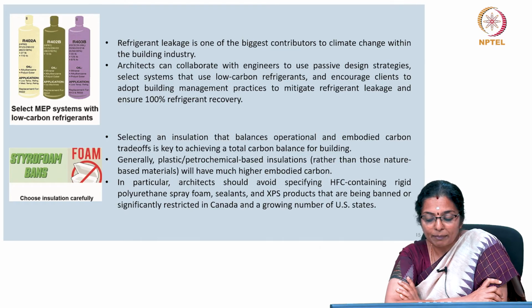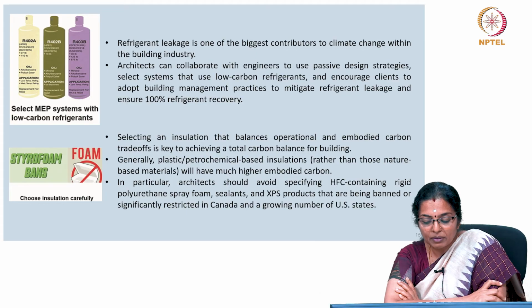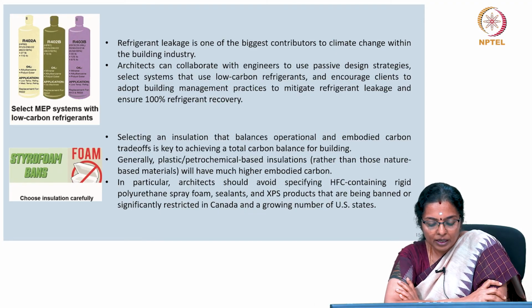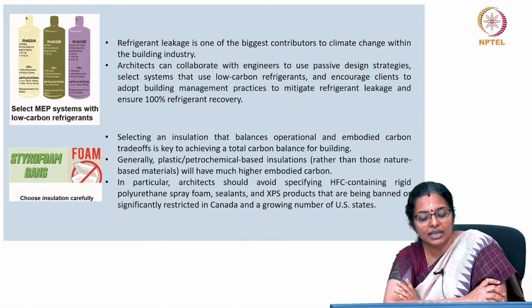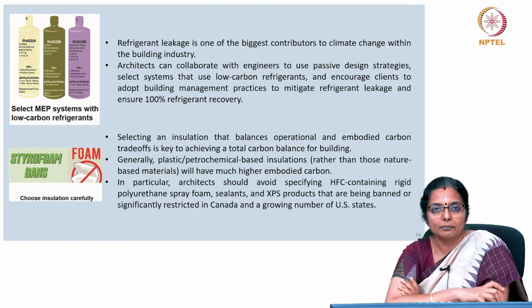Selecting an insulation that balances operational and embodied carbon trade-offs is key to achieving a total carbon balance for a building. Generally, plastics, petrochemical based insulation rather than nature based or agro based will have much higher embodied carbon. In particular, architects should avoid specifying HFC containing rigid polyurethane spray foam, sealants and XPS products that are being banned or significantly restricted in Canada and a growing number of United States.